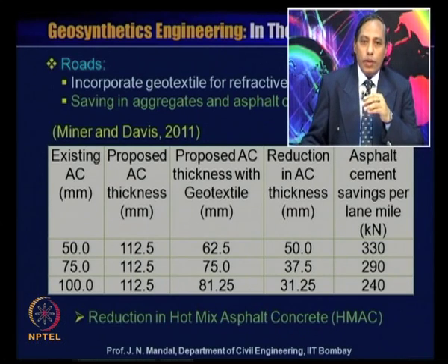So if you use that geosynthetics material, the proposed AC thickness with geotextile is 62.5 millimeter, 75 millimeter, 81.25 millimeter.